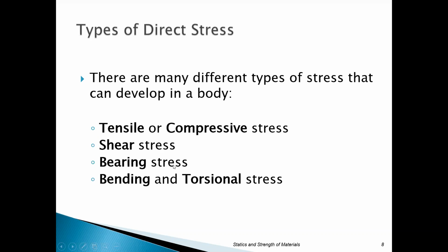Then the shearing stress, the stress develops parallel with the force essentially. And what happens in this, the area of resistance is also parallel with the force that's being applied. Bearing stress is kind of a ripping type of thing where you have something trying to pull something out. Like if you drill a hole in a part, you put a bolt there and you pull that plate, that bolt, if it stays intact, might try to rip a piece out of it. That's what we call a bearing stress.